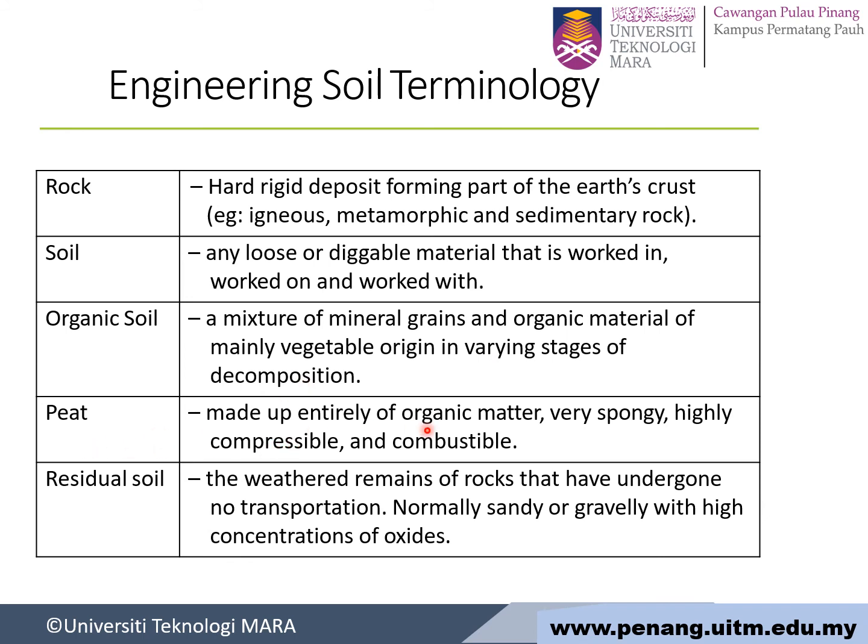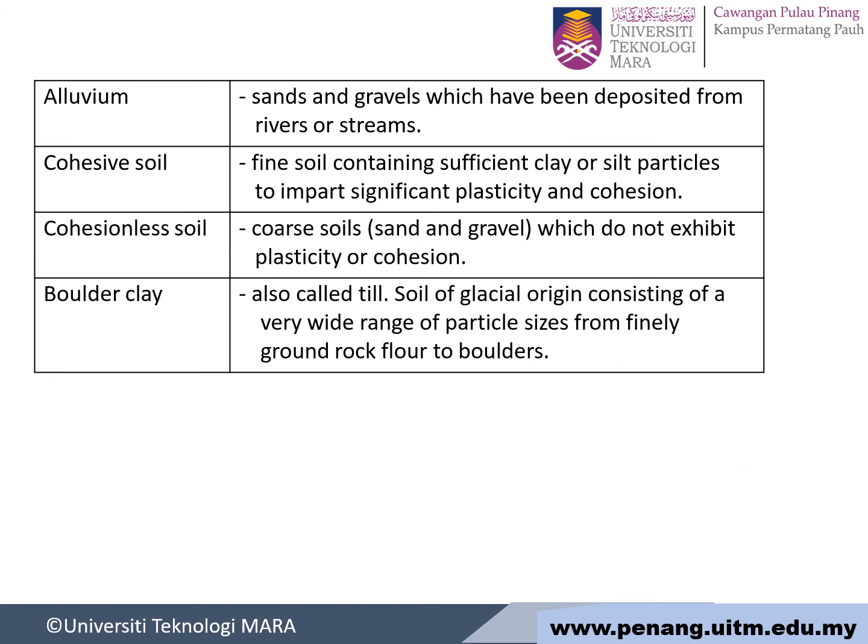Peat is made up entirely of organic matter, very spongy, highly compressible and combustible. And the last one is residual soil, the weathered remains of rock that have undergone no transportation, normally sandy or gravelly with a high concentration of oxide.